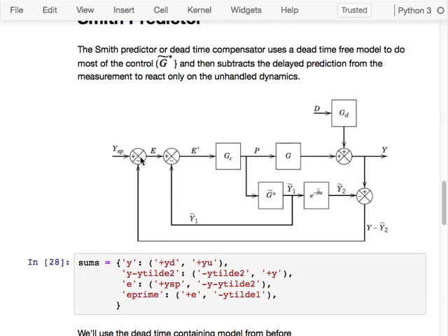And so the system has to wait for that disturbance to be felt all the way through to there. And so in this particular case, our disturbance transfer function is delay-free. But you can see that if there are dynamics in D, that is unavoidable. There's no way that I can preempt that using just a normal feedback system. Of course, if I had the ability to add a feed forward here, I could improve the disturbance rejection as well.